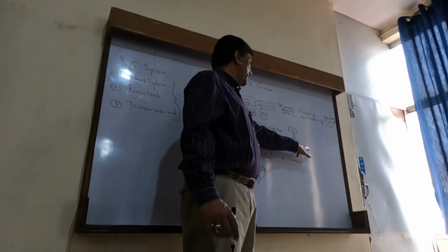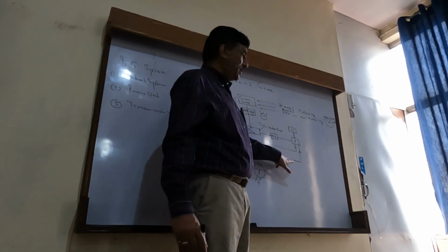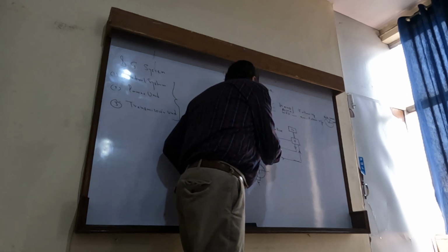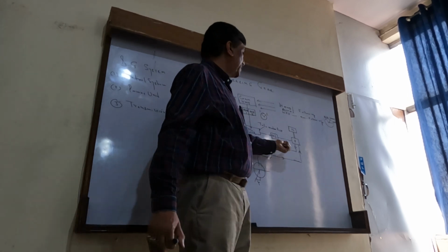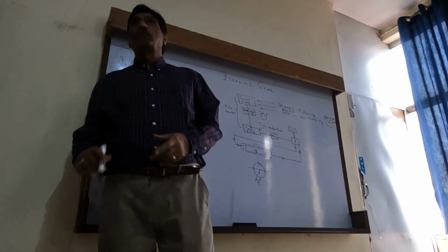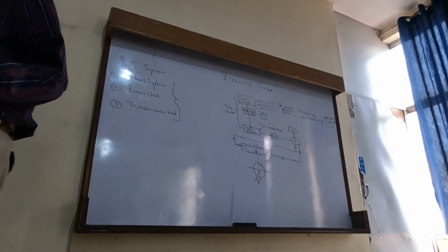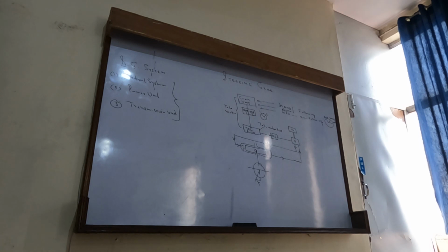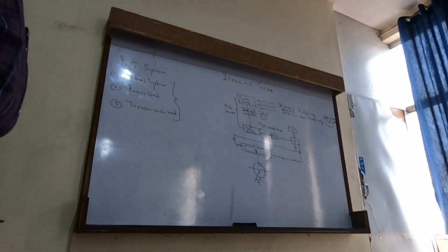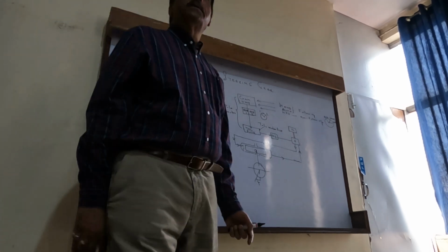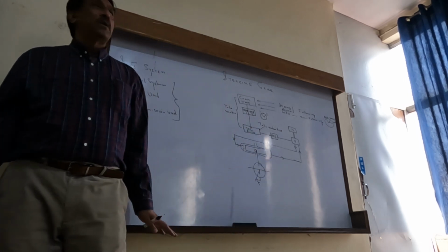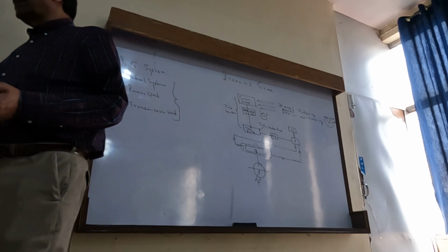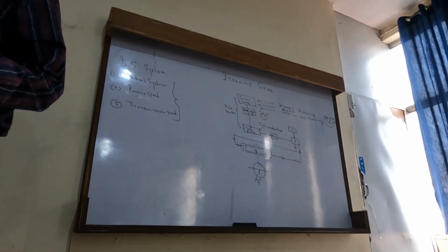Let us consider I want to give starboard movement. Then this will become my high pressure line or discharge line. Oil pressure will act this side and ram will move in the opposite direction. Return will be this. So always based on port or starboard movement, one is high pressure line, one is return line. How much is the pressure normally in a 2 ram steering? It is approximately 200 bar. 200, 215, 216, it is in this range.